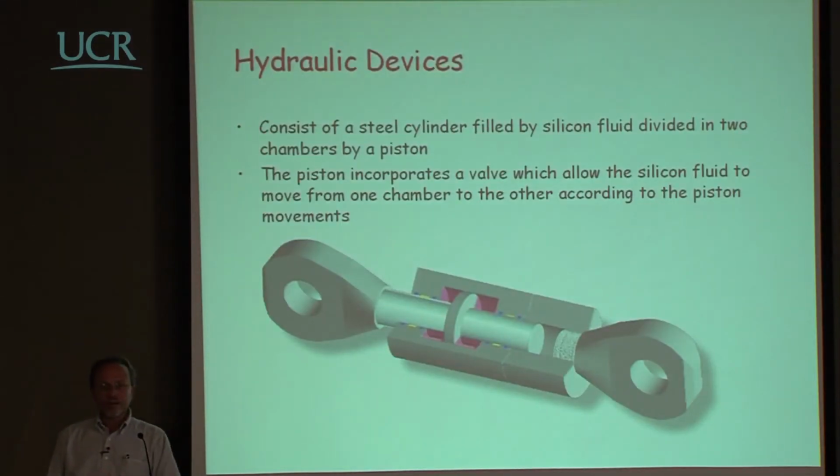Okay, I already talked. The only one I will say something more about is dampers. So this is not to take any vertical capacity, it's just to correct the response of a structure, what are called hydraulic dampers. These are very interesting devices, particularly, for example, when you're dealing with large bridges.